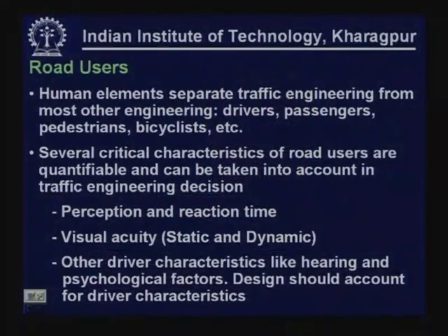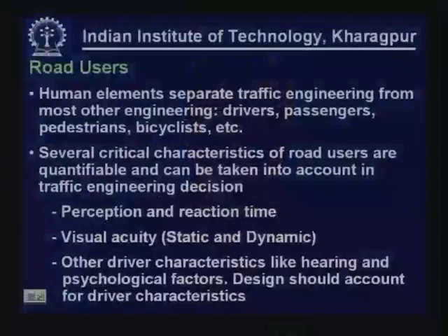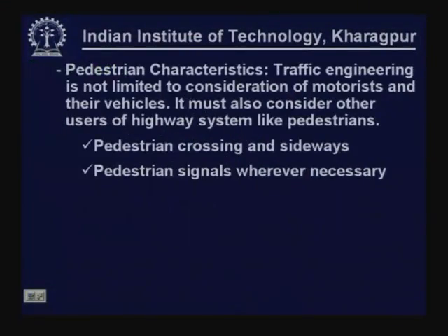For example, perception and reaction time of drivers, visual acuity, both static and dynamic. Most of the cases we check only the static visual acuity, but dynamic visual acuity also may influence the overall behavior. Then other driving characteristics like hearing, psychological factors. So, design should account for all these driver characteristics. You will see that in the geometric design part, we will discuss in detail how we can consider these aspects, road users' aspects, in the design process.